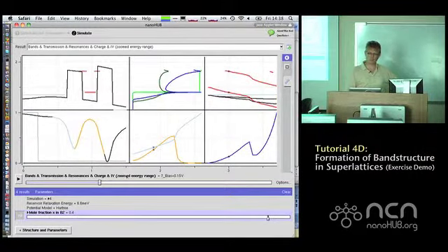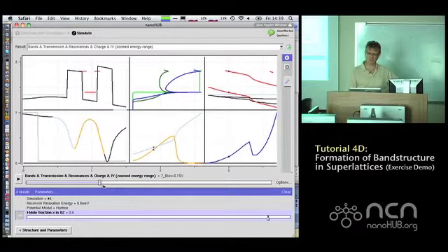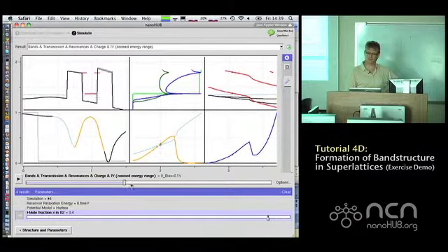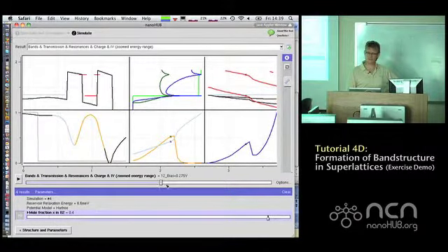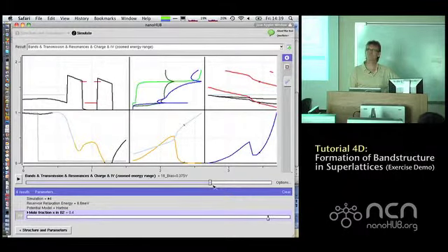You see it in this plot, how charge is accumulating inside the well more and more, until the electrostatic potential that is applied is strong enough to pull that full bucket, the charge bucket, or the bobber, that is trying to float up, all the way down. And when you pull it all the way down, it empties out.